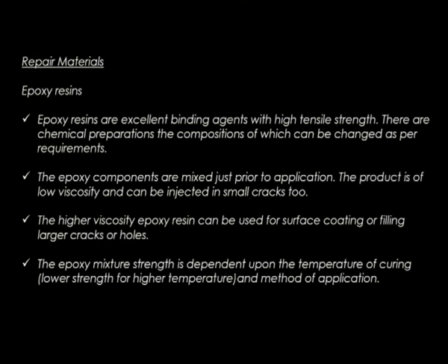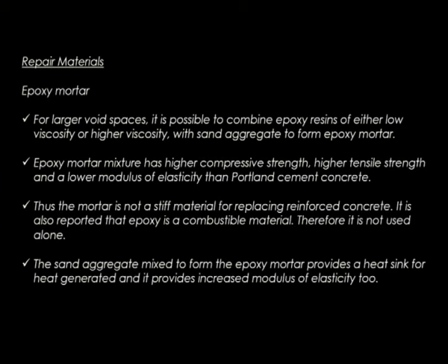The higher viscosity epoxy resin can be used for surface coating or filling larger cracks or holes. The epoxy mixture strength is dependent upon the temperature of curing, lower strength at the highest temperature, and method of application. For larger void spaces, it is possible to combine epoxy resins of either low viscosity or higher viscosity with sand aggregate to form epoxy mortar.